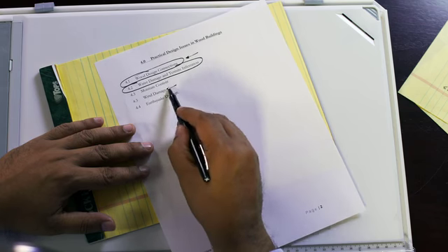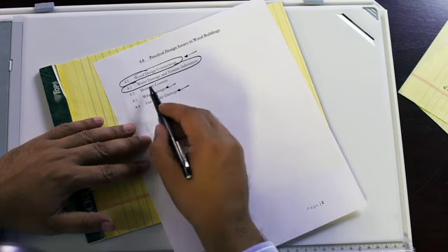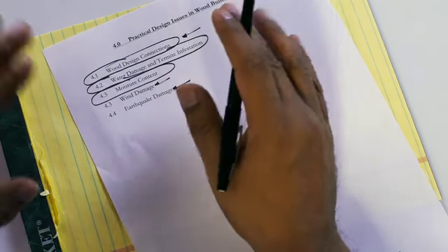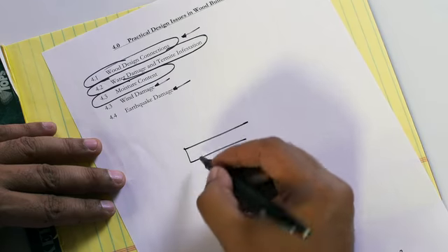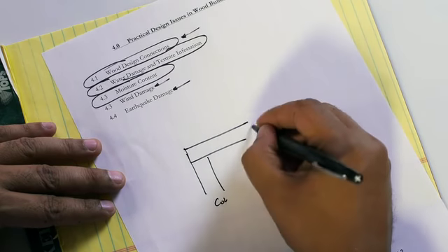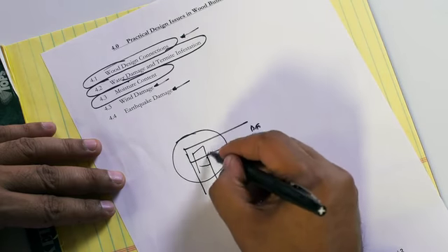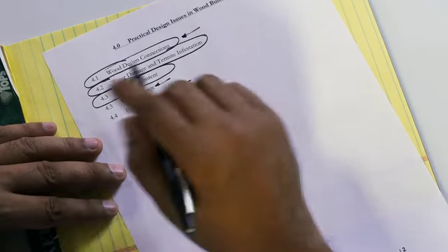And I want to show you some examples. Of course, you see a lot of wind damage, you see a lot of earthquake damage when earthquakes occur, but by far, if I had to pinpoint of all the wood failures that I examine, the top 3 big problems: connections, which is where my beam comes in to meet my column. This connection in here is a problem. It ends up with cracking, ends up with all kinds of issues. And the other one is wood damage with termites.